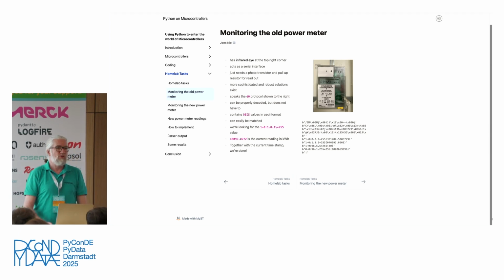You just need a phototransistor and a resistor. Attach the resistor to the supply voltage and the phototransistor to your ground, and the optical interface, properly placed, will then switch the transistor on and off, which gives you the data stream that you can read from your serial interface. That's quite simple. And below that photo is what you get. It looks complicated, although it really isn't.